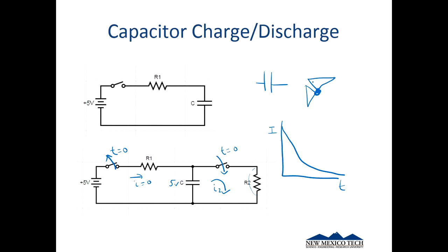As I turn the knob, this one goes this way, and parts of the plates cover each other up and make a bigger area. A bigger area means more capacitance, since there are more places for the charge to collect, so bigger capacitance.